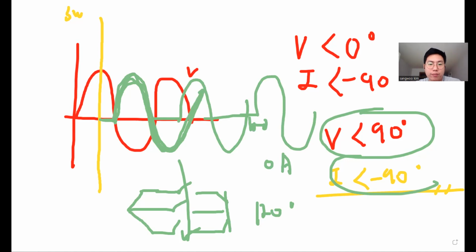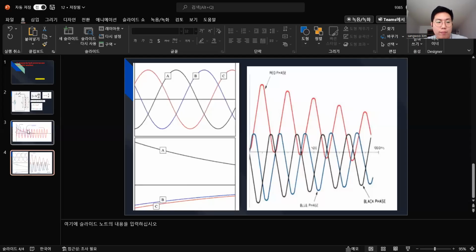Let's see here. So look at that. Oh yeah. So yeah, I explained that. And then look at that. We have a 3-phase system, right? So look at that. This A line. So the A waveform. This is, for example, minus 10 ampere here, right? And because of inertia, a DC offset here, plus 10 ampere happened. So that's why the standard line is here. The red line is this part like this. And what happened?